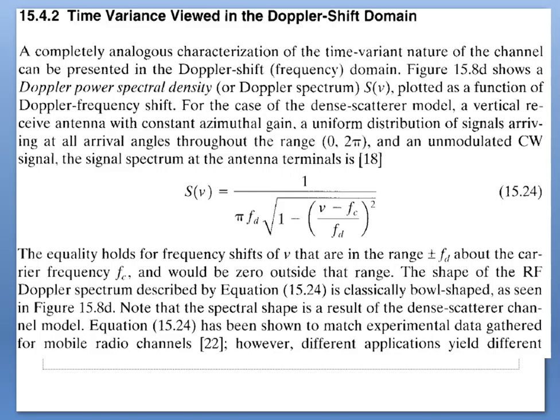In a typical multipath environment, the received signal travels over several reflected paths, each with a different distance and a different angle of arrival. The Doppler shift of each arriving path is generally different from that of other paths. The effect on the received signal manifests itself as a Doppler spreading of the transmitted signal rather than a shift.